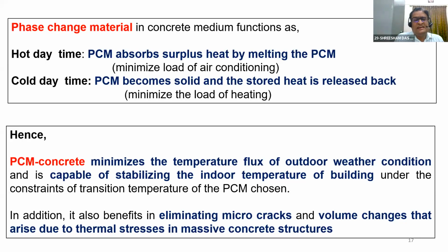That is the way it minimizes the heating load. Hence the PCM concrete minimizes the temperature flux of outdoor weather conditions and is capable of stabilizing the indoor temperature of the building, within the constraints of the transition temperature of the PCM you chose.